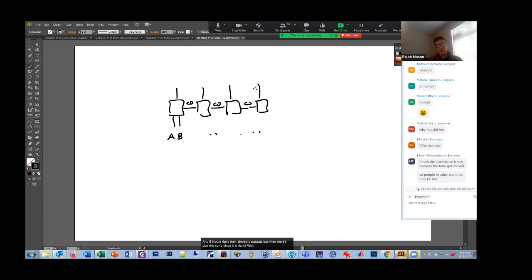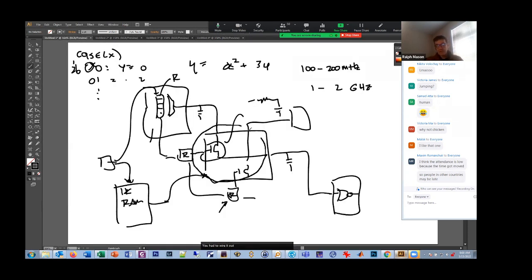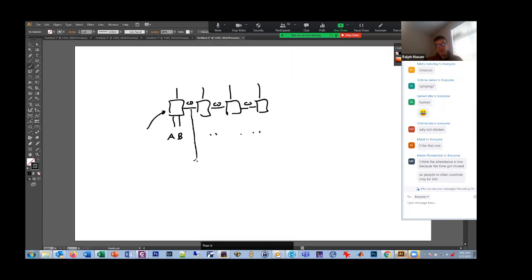Well, if this 1 adder block was in 1 LUT, and then you had to wire it out through this switching matrix to another block, then you can get a lot of delay if you're going through the switching matrix.